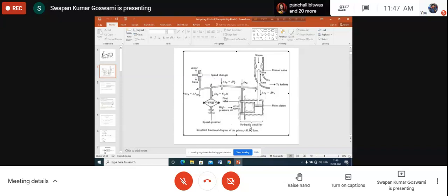That's why we are controlling the power supply to the load. Frequency variation is due to the variation in the power demand, and the mismatch between the power demand and power generation is the sole reason for frequency variation. So when we control the frequency, we are controlling it in response to the variation in load. That's why it is called load frequency control. And why automatic? That will be clear to you after I discuss this whole thing.